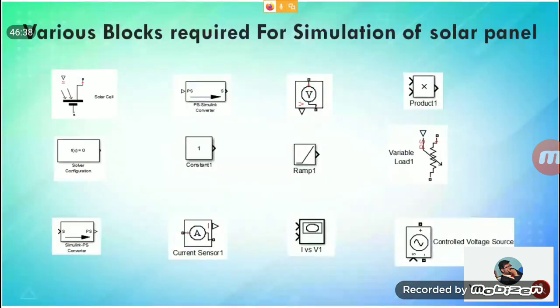Okay. Now let us see, for simulation of a solar panel, what blocks are required. You can take down what blocks are required. First and foremost block is the solar cell. With the help of this solar cell, I will add cells and try to generate the required voltage. Since this is from Simscape, I cannot directly connect it to Simulink, so I need a PS-Simulink converter as well as S to PS. So PS to S and S to PS are required, and Simscape will work with a different solver.